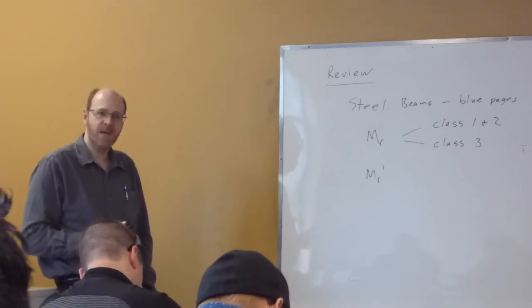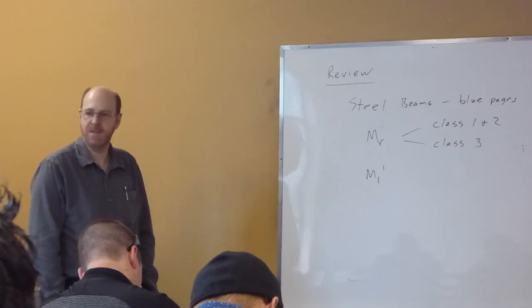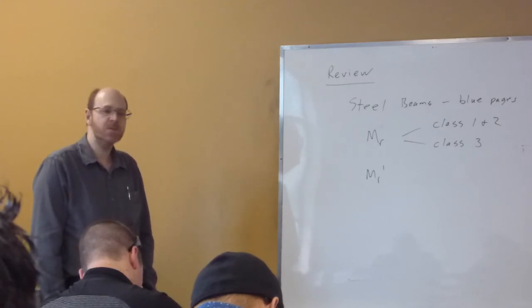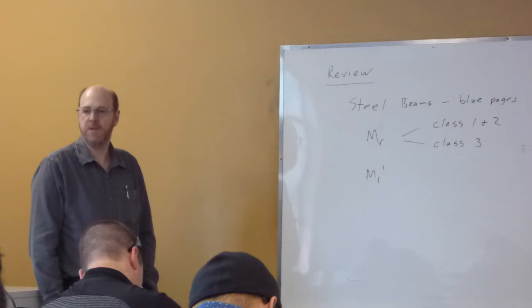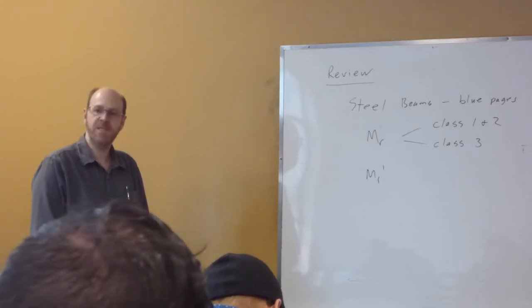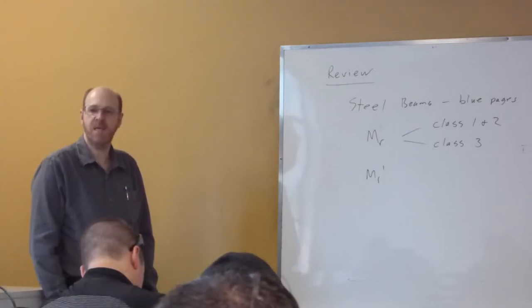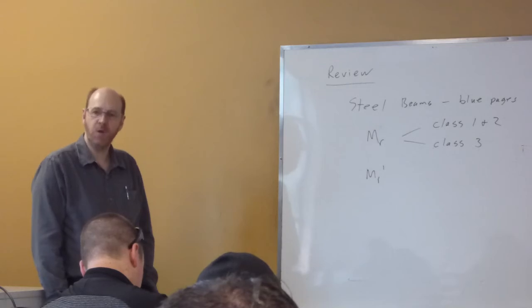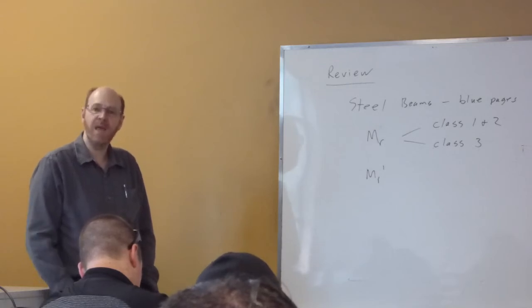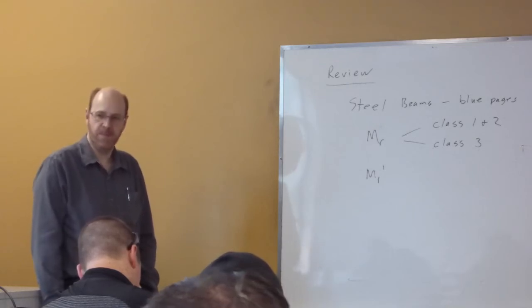So since that steel deck is not physically connected to the beam yet, that means we have no lateral support on the top flange. So we have to design our beam to be able to resist that construction load case with full length as the unsupported length.